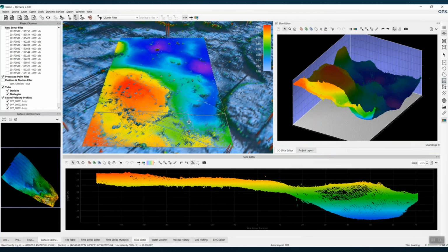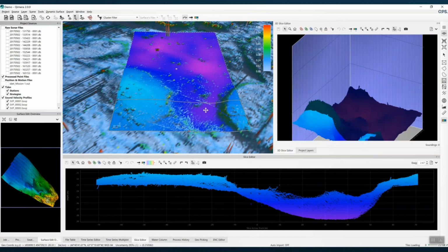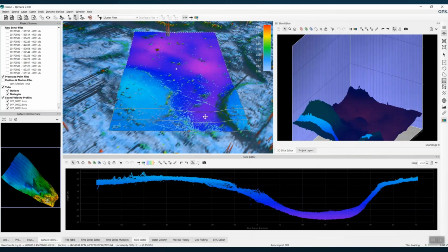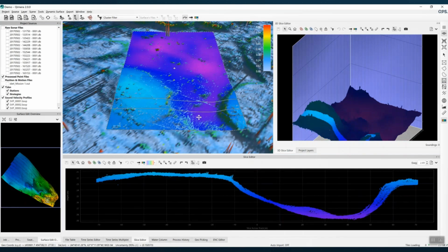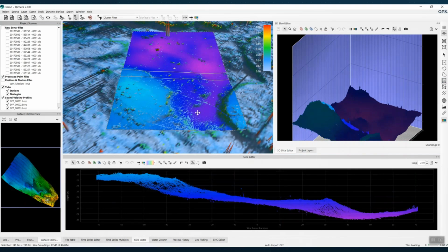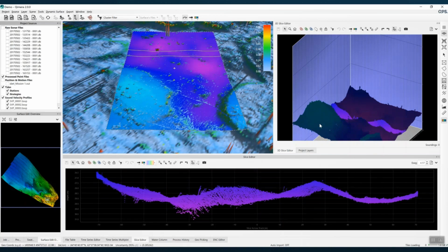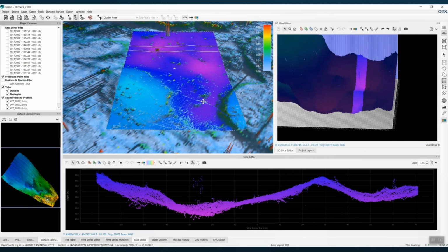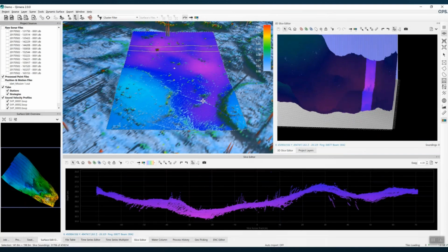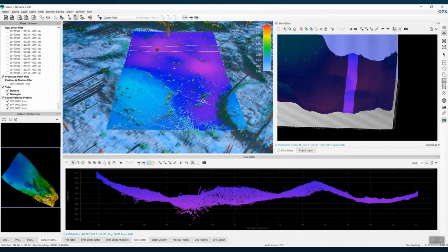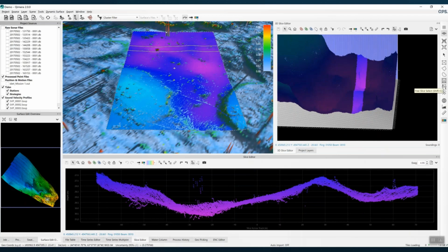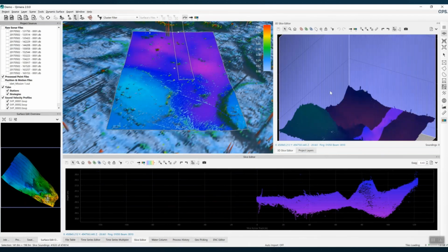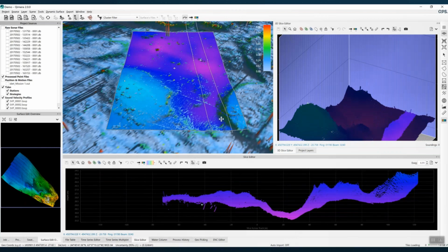So now we'll just look at a couple of other selection modes. This is the fixed slice select. So in this case, you can draw a box, and then there's a slice that's fixed within that box reference frame, and you can only advance it forward and backward. And you can see that the soundings light up differently in the slice editor versus the 3D slice. And when you edit in the 3D slice, it only edits the ones that are loaded in the current slice, so the highlighted soundings. So you can have the full context of the other soundings, but when you lasso and kill dots, you're only editing in the highlighted ones.